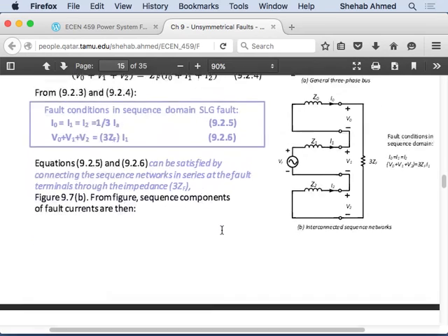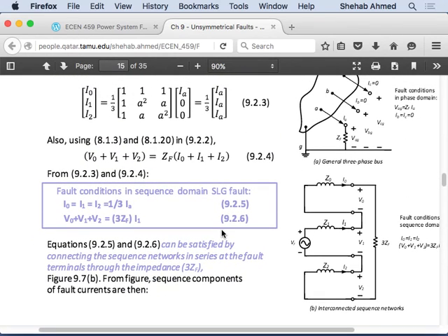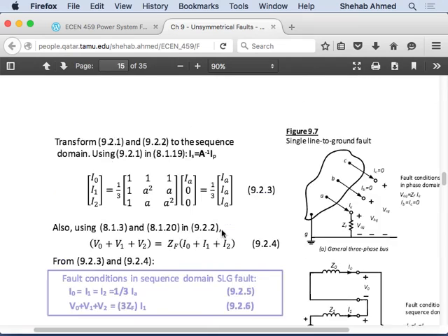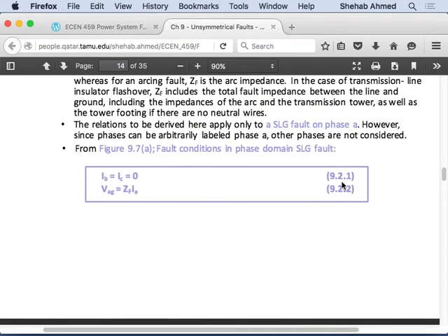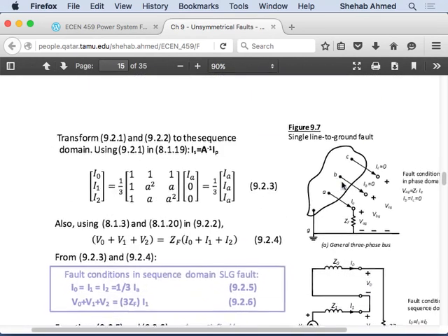So we'll stop here. It's a very similar process for the double line to ground and double line faults. We will just have some input conditions based on our assumptions. Other phases with no fault current will have zero current flowing through them. And then we will look at calculating the fault voltage. What is this fault voltage equal to? If it's a double line to ground fault, it will equal the current coming from the two phases flowing into the fault. And we will use that to come up with my output conditions.